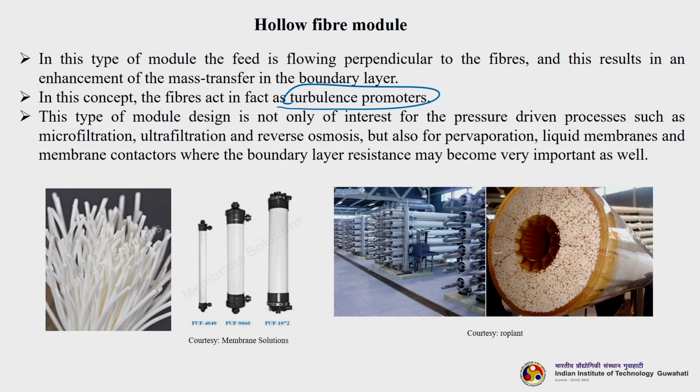So, this type of module design is of interest not only for the pressure driven processes such as microfiltration, ultrafiltration, RO, but also for any other system like pervaporation, liquid membrane and membrane contactors. So, you can see these are single hollow fibers. This is one single hollow fiber, this is one, there are so many hollow fibers. So, they are joined together and form a module, and the module looks like this.